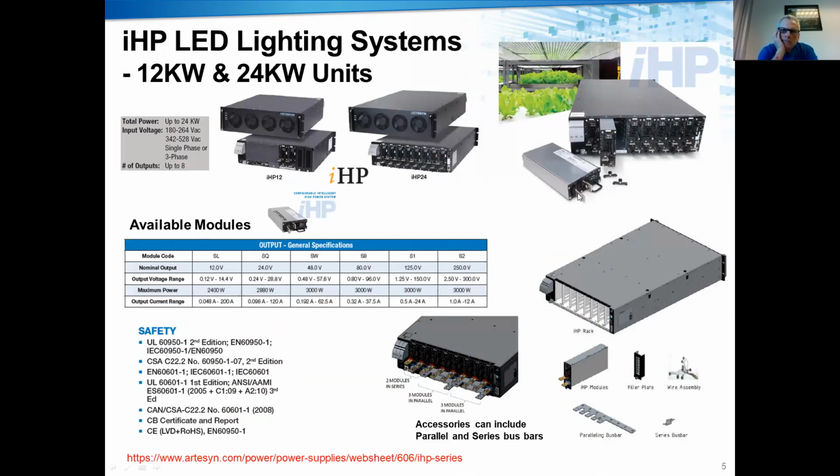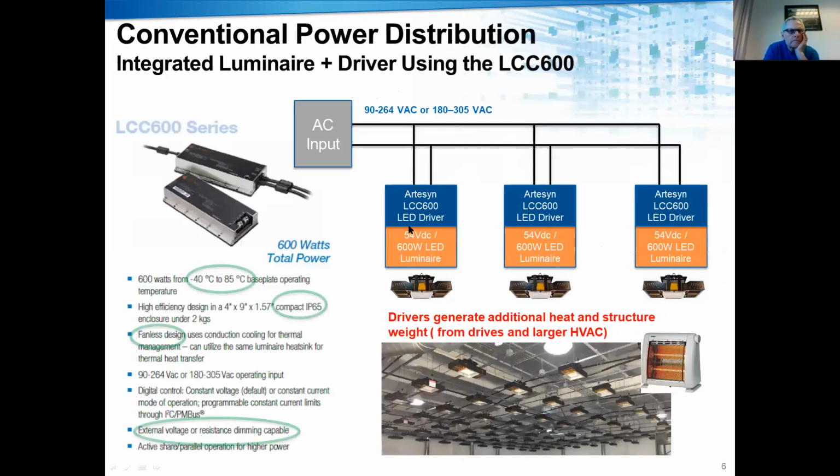Each module is independent and very smart. You can set up scheduling, dimming, you can do voltage mode, current mode, analog current mode, a lot that I'm going to talk about a little bit. And actually you can put these in series. There's a 250 watt module. We have a customer using 400 watt lights, so we're going to put 2 in series. Anyway, this is the equipment we're going to be talking about, the 3,000 watt modules.